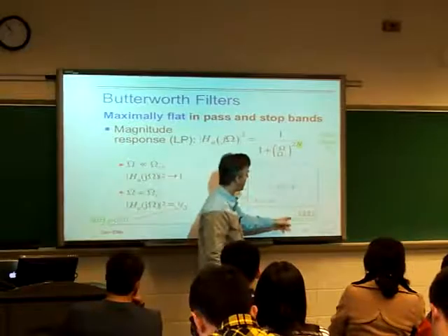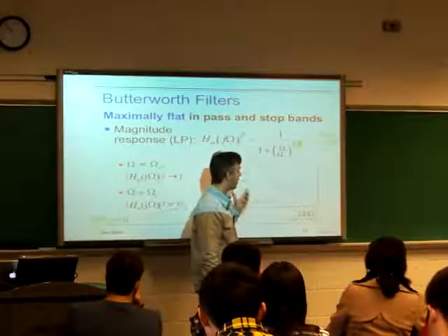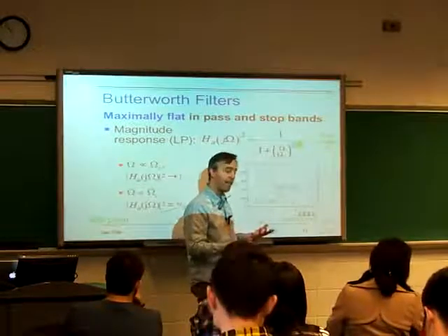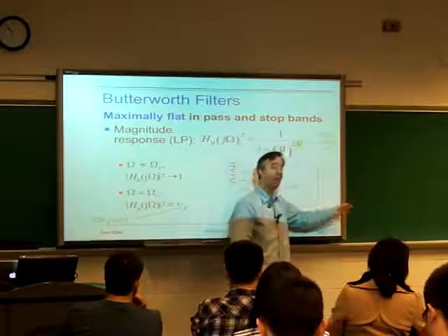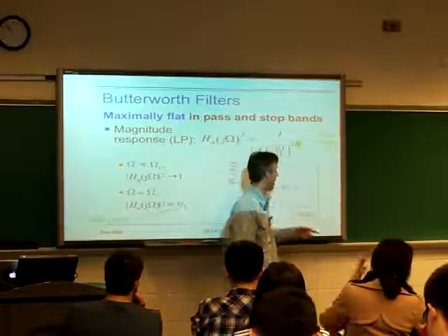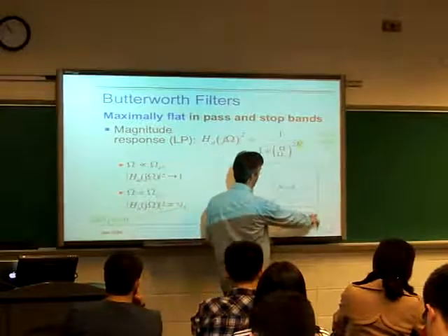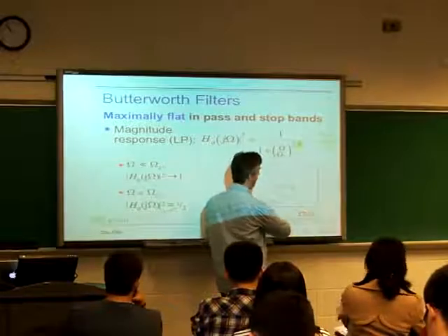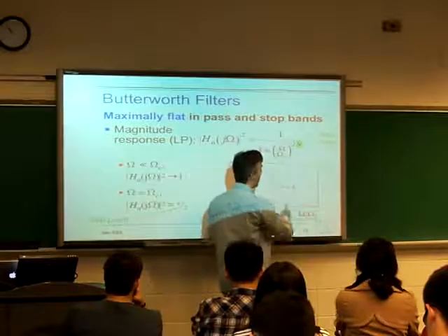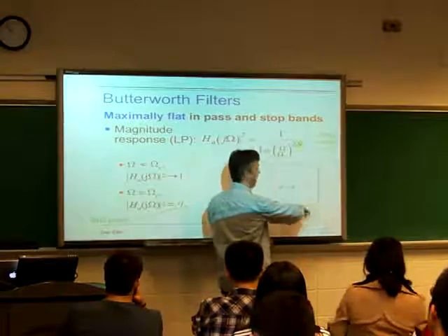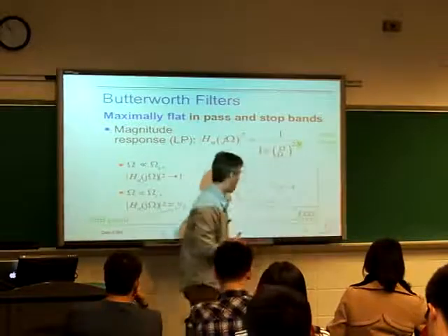Notice that on this frequency response, we're now dealing with capital omega, which is my convention for analog frequency, radians per second. And of course, analog frequency has no upper limit. You can keep going faster and faster. They look like frequency responses we've had before, where the normalized frequency, radians per sample, would go up to pi, and then at pi everything would stop because that's where we start getting aliasing. Here there's no upper limit, so when we draw these we just have to stop at some point, but it will carry on like this forever.